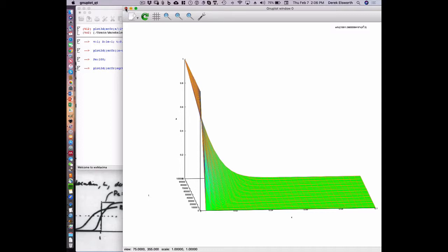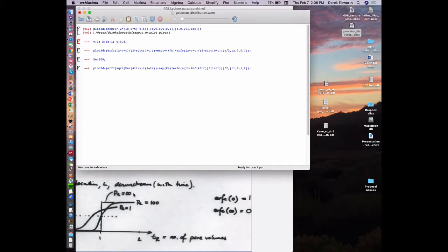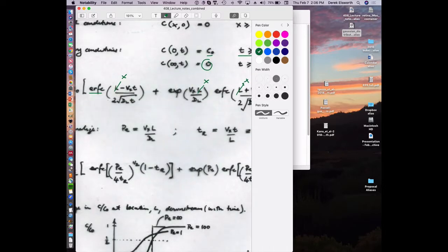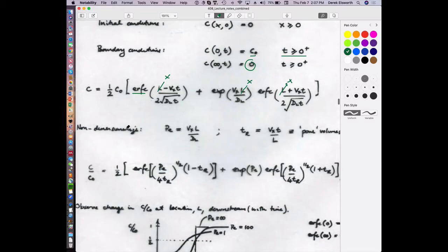We'd like to know the case where diffusion and dispersion can occur, as it does here, but also with advection overlain on top of it. And so we can look at this expression that we have here, which looks like a complicated equation, but it's just a length, the advective velocity, the time when we want to get the plume defined, and a coefficient that describes the dispersion in the system. And these terms actually recur.